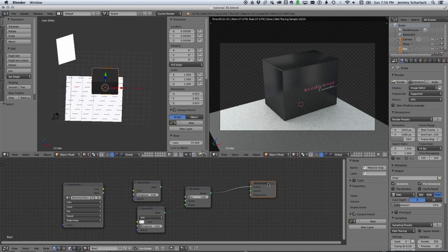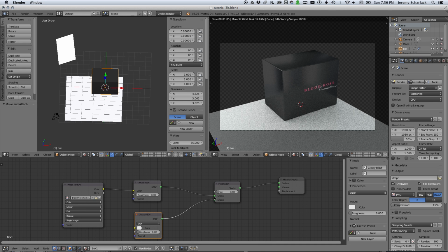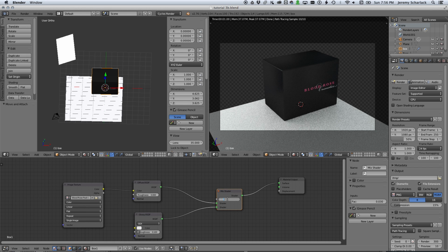And it's actually really quite glossy looking now. So I think we want to turn that pretty far down. So maybe 0.03, so it's only a very slight gloss. In fact, I might even go 0.1 here. So yeah, there we go. That's a very slight gloss, it's clearly glossy, but not super glossy. Yeah, I might even turn this to like 0.01 or something. Maybe 0.02.